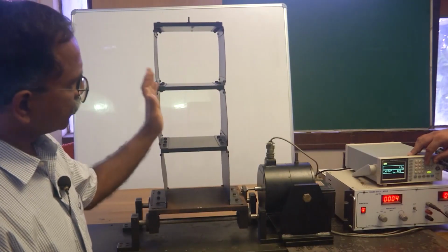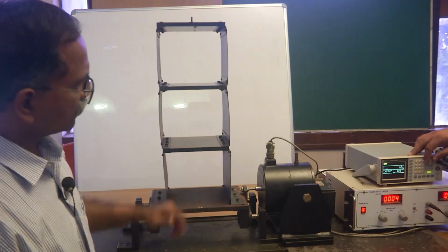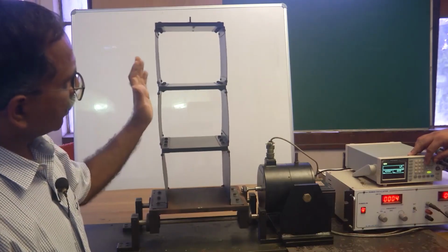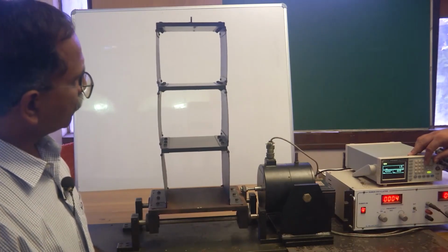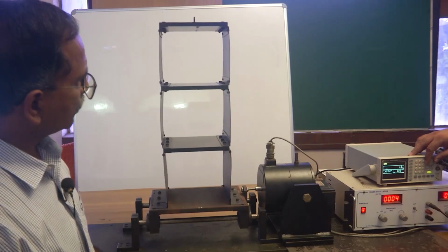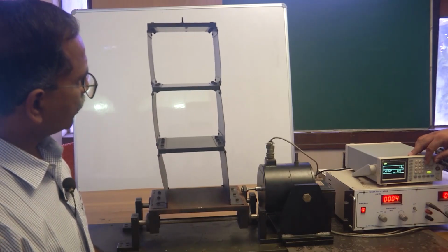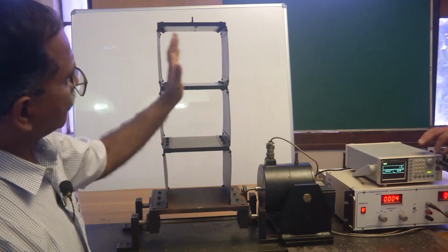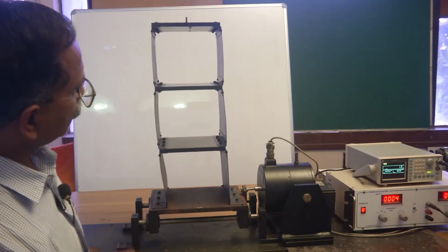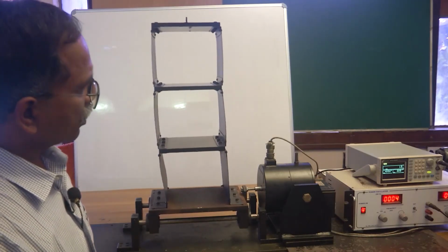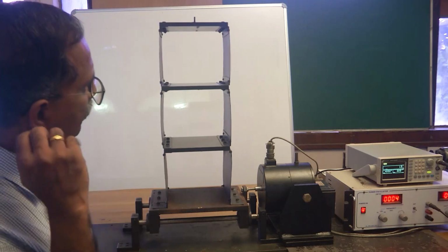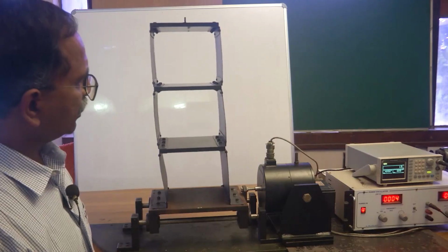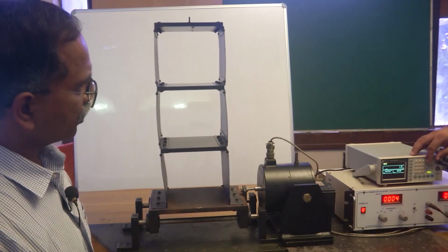Now you can see that the amplitudes of vibration here of all the floors have started increasing. At 1.2 the frequency of excitation, the amplitudes have again increased. Now when we move it to 1.3, you can see that the vibrations are quite strong, and all these 3 floors are moving in phase. You can see that if you play this video in slow motion, you may observe that all the 3 floors are moving in phase, and if this is the resonance corresponding to the first natural mode, then any increase in the excitation frequency will further reduce the amplitude of vibration.